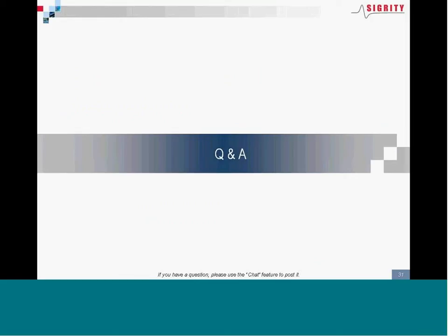Okay, so that's a good question, and actually it's a pretty common misconception. Everybody thinks when you're doing serial link analysis, you have to have IBIS AMI models, and if you don't, you can't do the analysis. So it's actually not true. IBIS AMI models are required for the SerDes devices that use adaptive equalization, that adapt on the fly to the channel. Very difficult to do those with circuit models, so I would say mandatory usage for those types of SerDes applications.